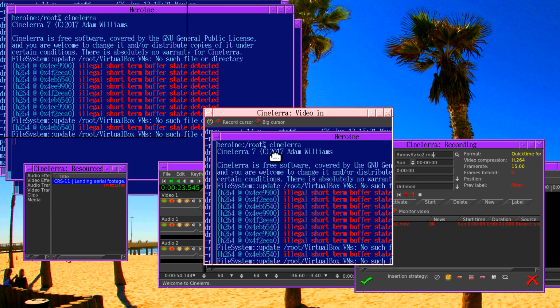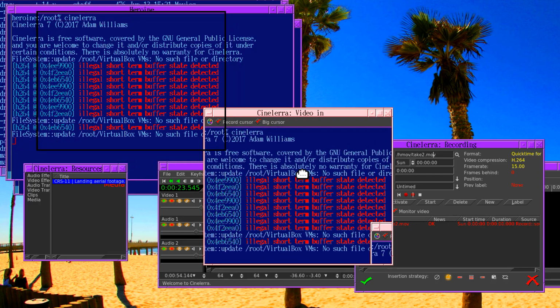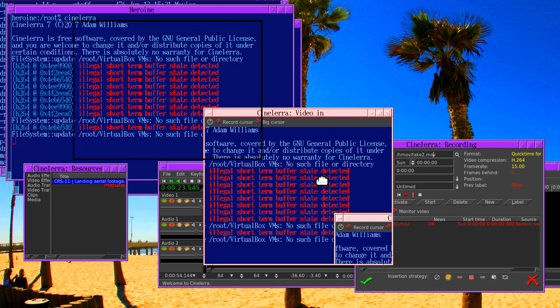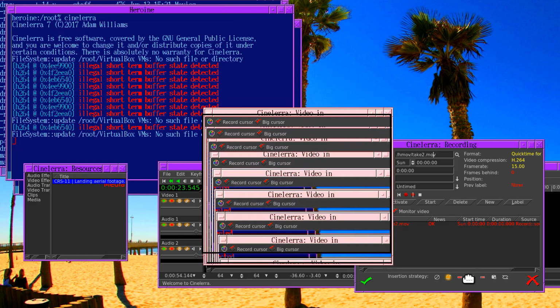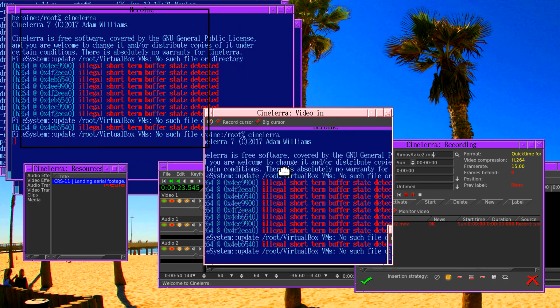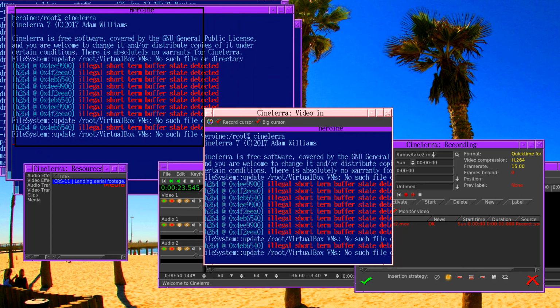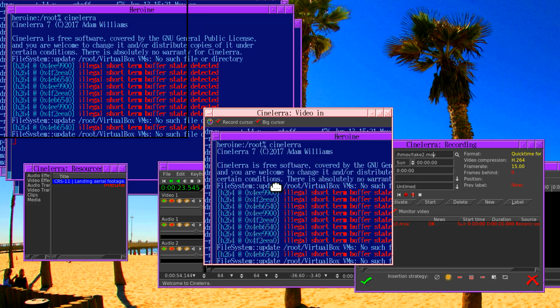To reposition the recorded region, click inside the monitor and drag it to move the window that's recorded. There's now a black border on the actual screen to show what content is being recorded. Right-click inside the monitor and select Reset Translation to reset the recorded position.